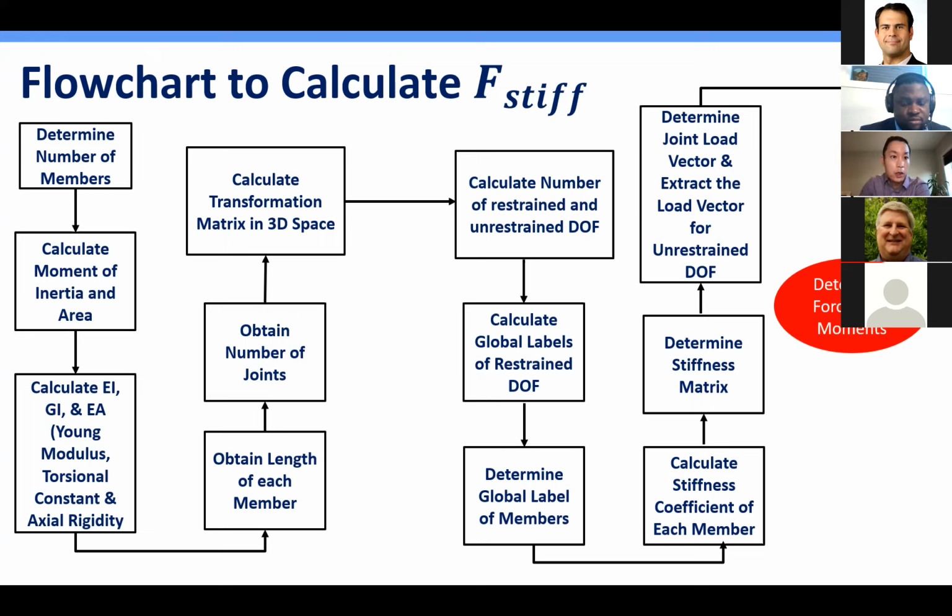Okay, thanks. Just one question on another piece. You mentioned one of the pitfalls of the stiff string and the finite element analysis is the computational complexity of the problem. Part of that is setting up or identifying the number of elements and setting up the mesh, arranging the grid, right? Say you have a drill string that's 15,000 feet or so, exactly how do you go about setting up your mesh, and what goes into determining how dense it is? Is it wellbore trajectory? Is it just the length of the drill string? Is it contact points, for example stabilizers that are around it, where the grid gets more dense? Just wondering if you can comment on that.